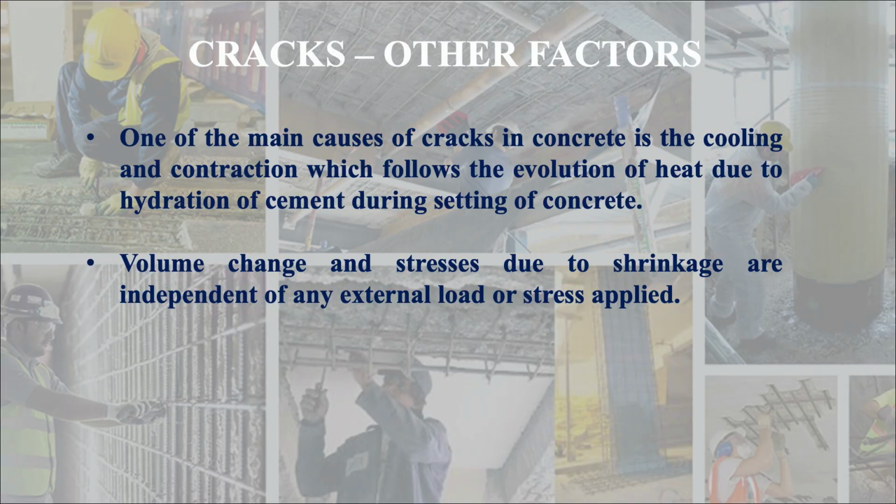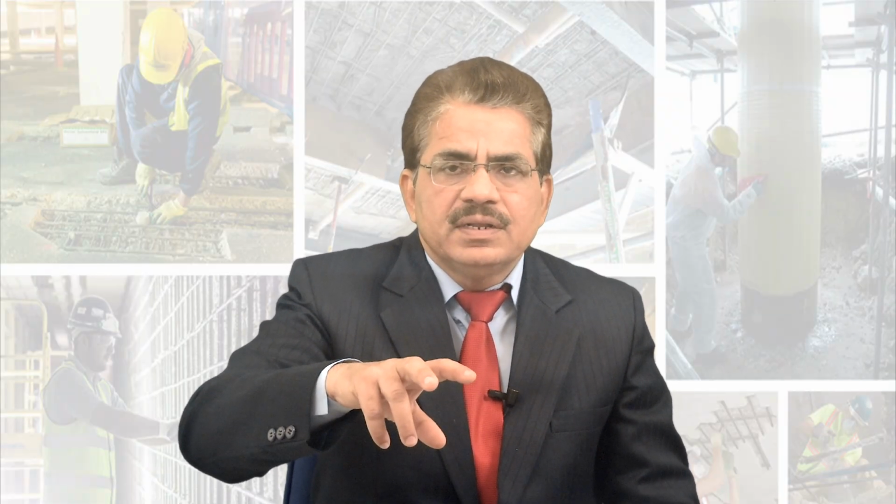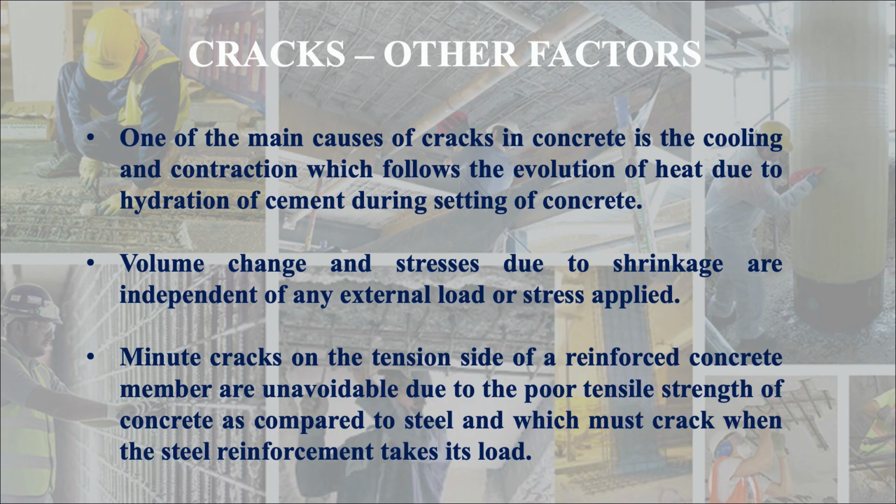Volume change and stresses due to shrinkage are independent of any external load or stress applied. Means even if some external load is not there, the volume change and stresses due to shrinkage will be there. Minute cracks on the tension side of a reinforced concrete member are unavoidable due to the poor tensile strength of concrete as compared to steel, and which must crack when the steel reinforcement takes its load.